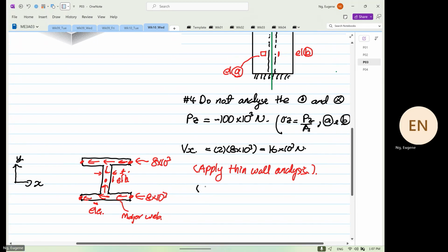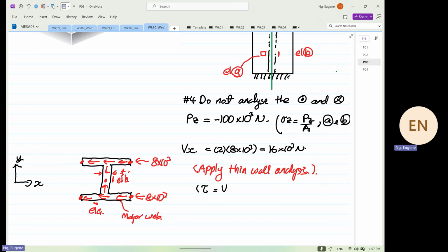So from here, you can specify that the shear will be equal to Vx over Iyy times Qy over t. We know that at A it is not equal to 0, at B it is equal to 0. Divide your analysis into sections, or you'll go bonkers. Yes or no? Small sections are easier to visualize. What's next?